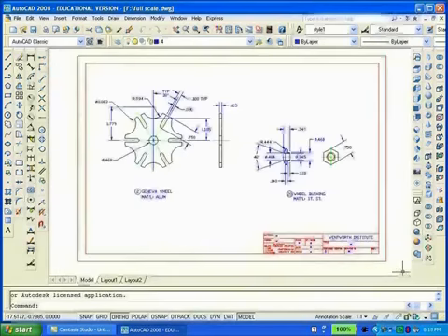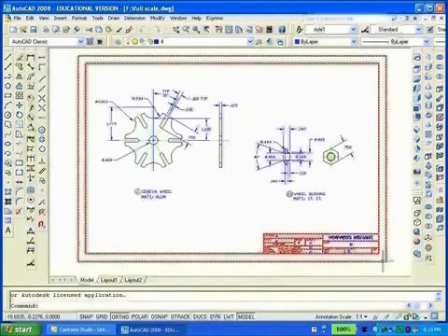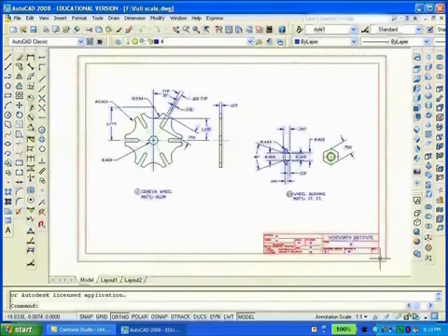On the other hand, if the Geneva drive wheel that I'm showing now is to be plotted at full scale or 1:1, and a B-size format is inserted, the drawing is not too large but fits properly. Here there is no need to scale the format.